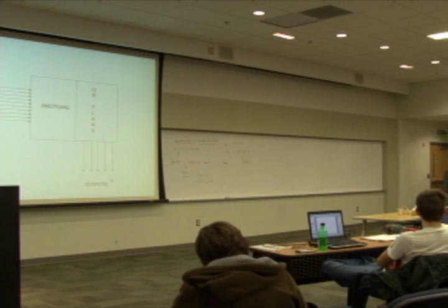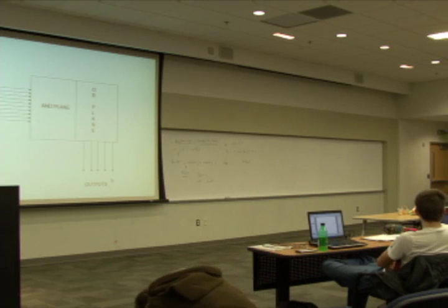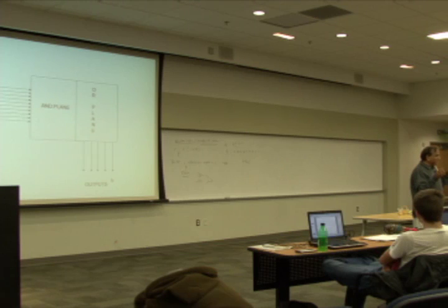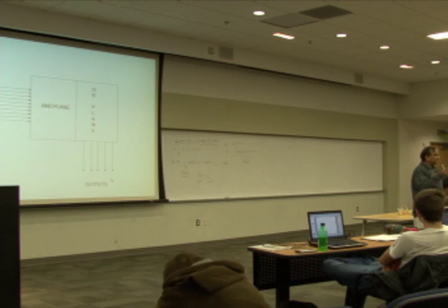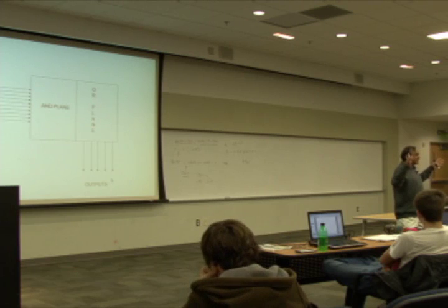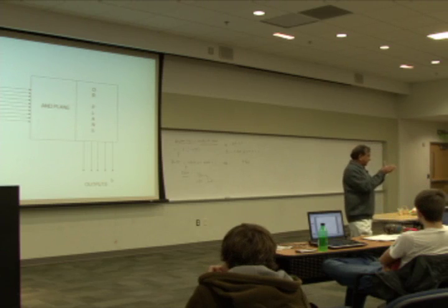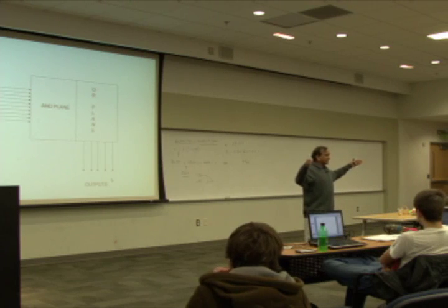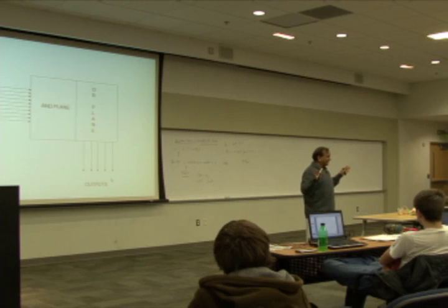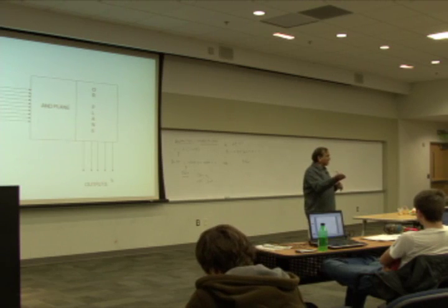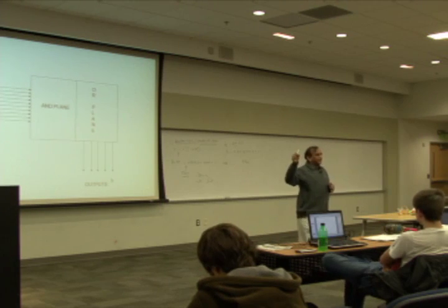Well, you talked about the Z bit, but elaborate on that. So think about the contents of the ROM. The contents of the ROM are all of the control signals, right? All those control signals needed in every clock cycle. Only a few of those are required, right? What you're doing is there's an enormous wastage of bits, because the word width of your ROM is as big as the number of control signals that you need in the entire data path. And if you start writing the sequence, you'll see that most of them are 0, right? So it's only a few of them that are ones.